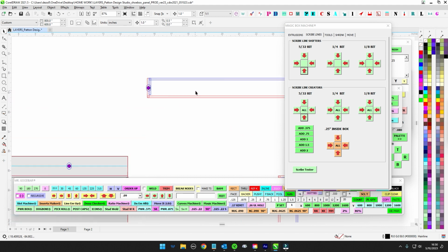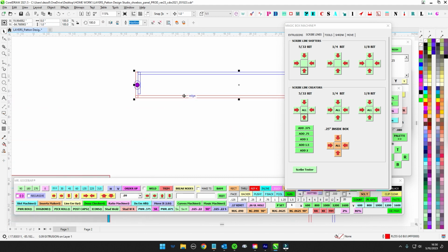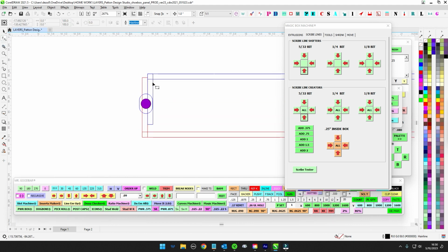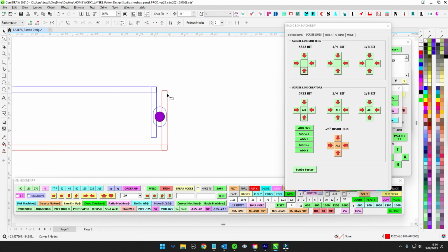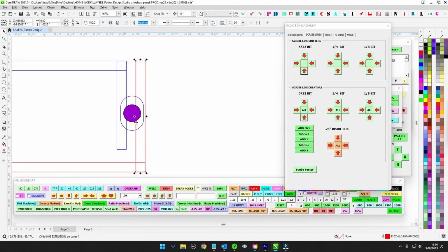Now, here's where you can make the decision as the designer. Do we just leave the 1/16 of an inch there? So when this thing grows a 1/16 of an inch, is that actually a good thing? I'll tell you what, most of the time, I leave the 1/16. I don't mess with it. Because what that does is that it allows just a little more room here.